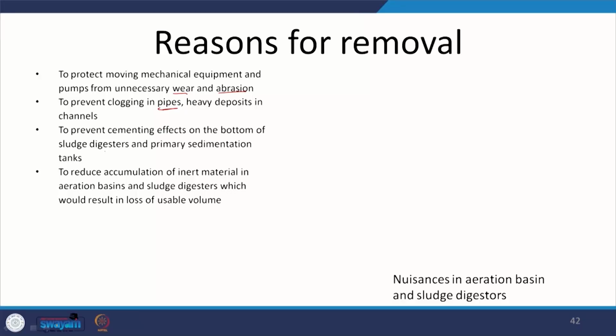There was a particular colony, and he wanted to use that for a particular pilot scale wastewater treatment plant. An MTech thesis here is typically done over 1 or 1.5 years, and in that period he spent around 9 months trying to unclog the relevant pipes. Why? Because a lot of plastic, rags and such always come into the system. So, not just plastics, and then grit, and that leads to maintenance issues. That is what I was trying to stress when I was giving the example.